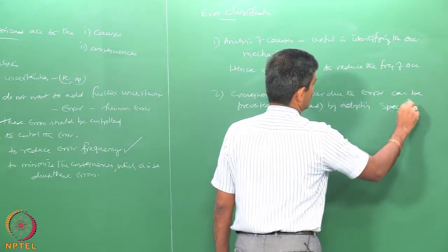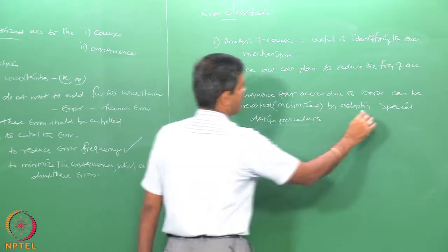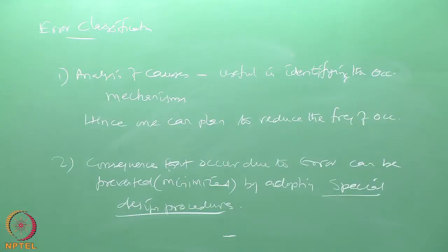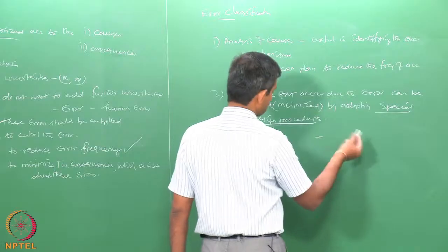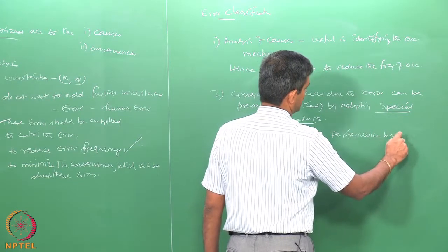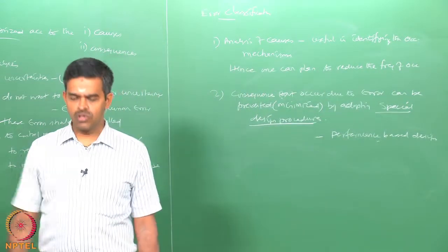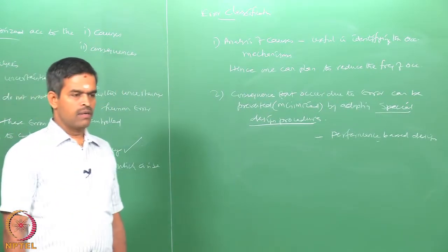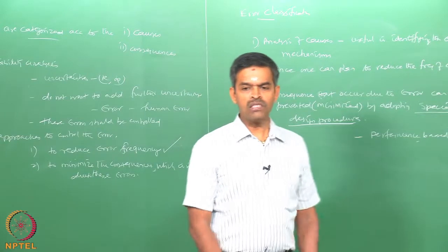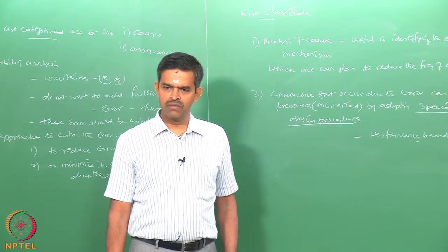special design procedures. We can name one very quickly. One could be performance based design. It can be one design approach which first highlights or emphasizes or pre-states what is the performance level required. Is it immediate occupancy, life safety, collapse prevention, etc.